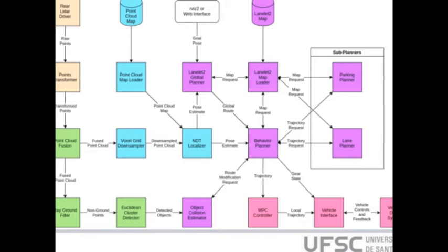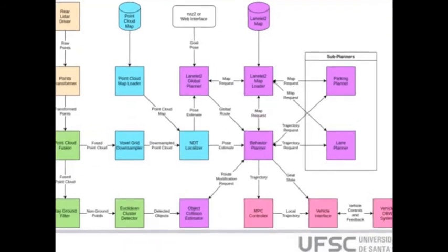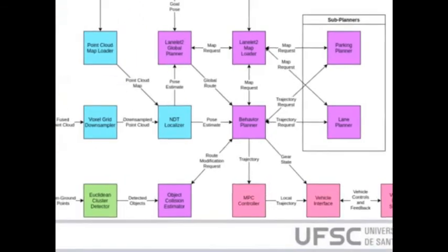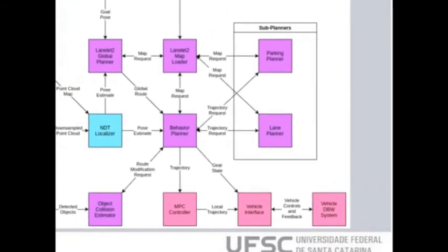And the behavior planner for the AVP planner that was available switches between the lane planner and the parking planner. That is, there are sub planners. In other words, the parking planner is used to park the car and the lane planner to follow the lane to find suitable parking spots. Because the first ODD covered the parking scenario, this is why we have just the parking planner and the lane planner here.